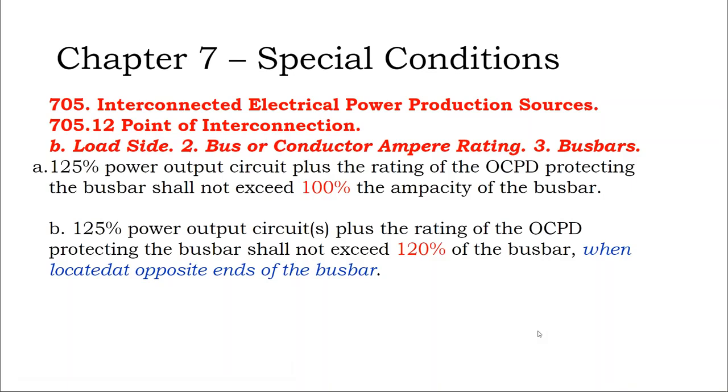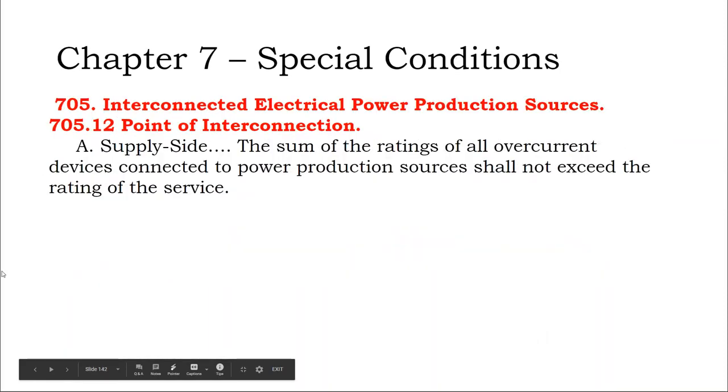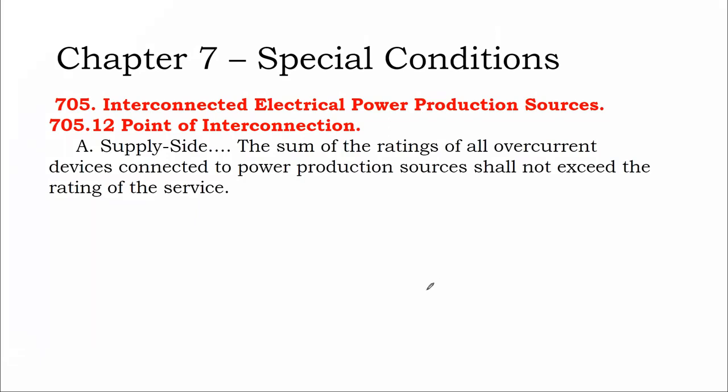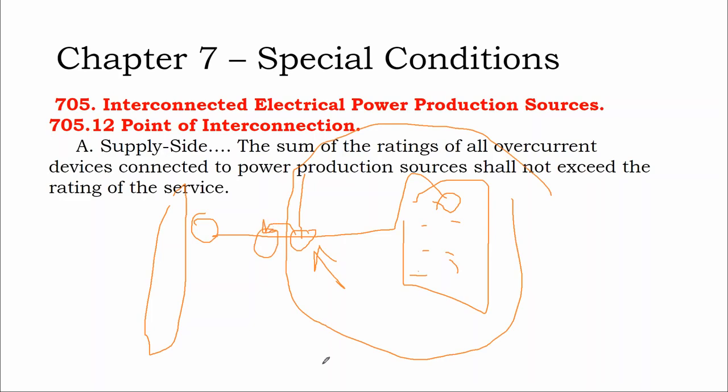If you're doing a supply side connection, you're putting in a larger system, because that lower amount doesn't work. And so if you have your electric service panel here, and you're intercepting these conductors between the grid and the solar array, you might want at this point to put in a 3-pole disconnect switch so that you can fully isolate the home.